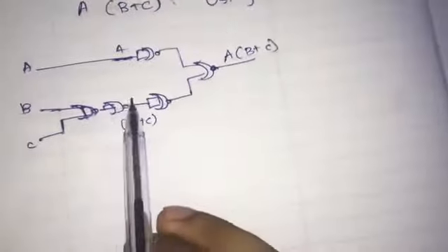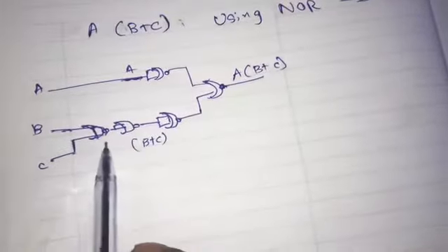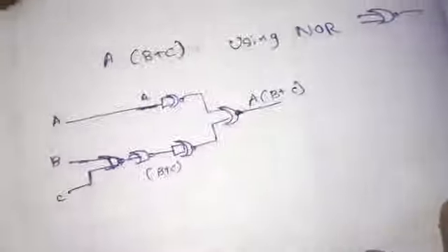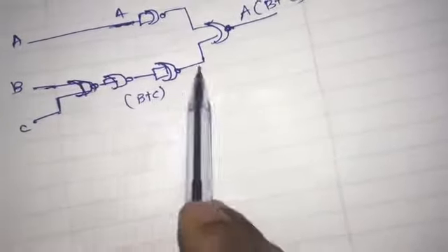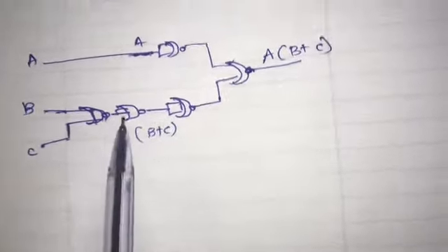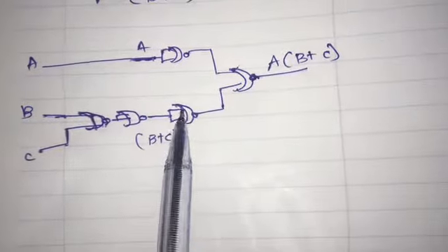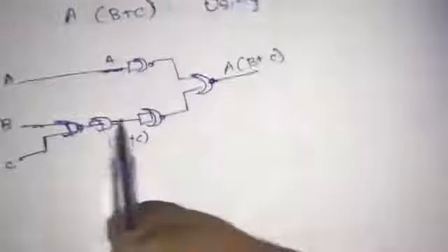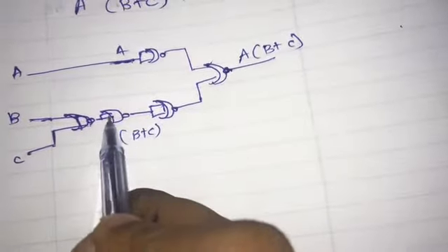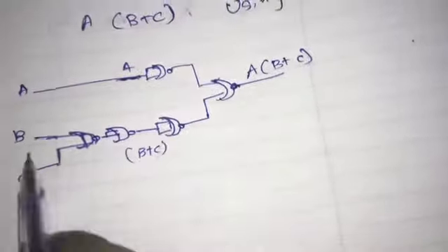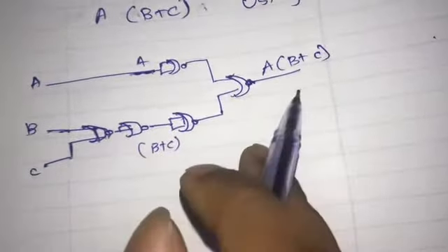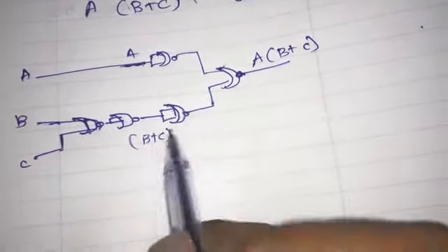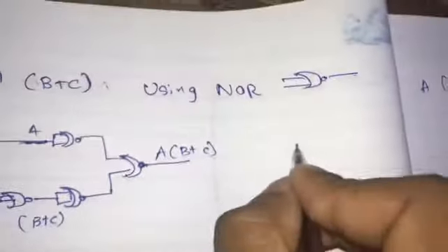But you have to simplify this. See, there's a lot of repetitive gates. How you simplify this is that if the same wire goes through the same gate twice in a row, you can cut them off. Since this is like a bar, this is a NOT gate. NOT is just the same wire, without using the gate.